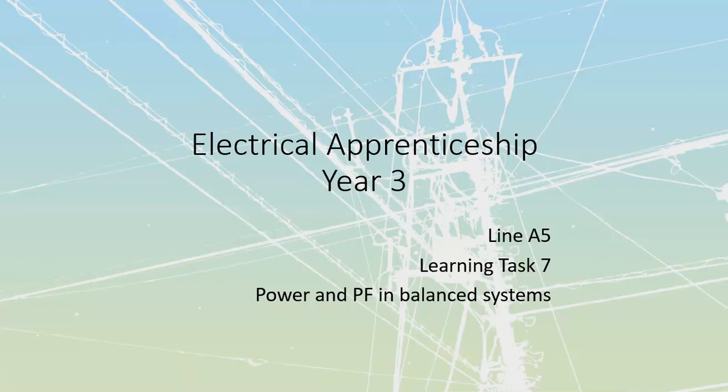Line A5, learning test number 7, we're going to take a look at power and power factor inside of balanced circuit systems. And I do want to note that it is inside of a balanced system. It's so important to understand that what we're learning inside of this one cannot be used in all installations. If you've got 3 different single-phase loads that you're connecting across from line to neutral on A and B and C, and they're all different, you're not going to be able to utilize a lot of the stuff that we see inside of this learning task. So just bear that in mind.